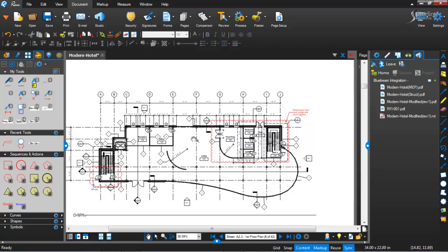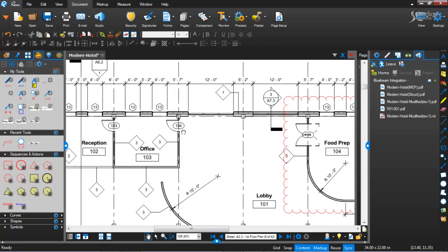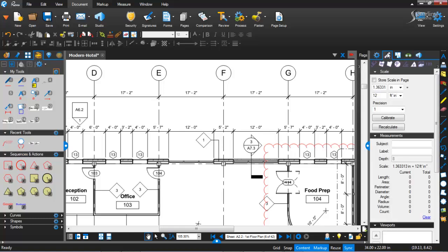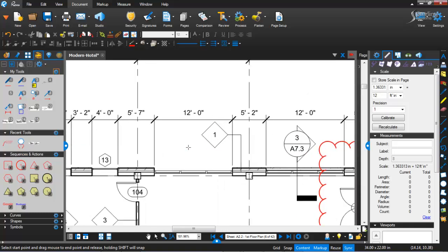Okay, another feature that allows you to really work up a PDF is the dimensioning tool. If we go to the measurement, and I've done this previously, so it's been saved, but there's a calibrate button that allows you to actually take a known dimension within a plan. This could be any scale, mind you, and be able to locate a dimension.